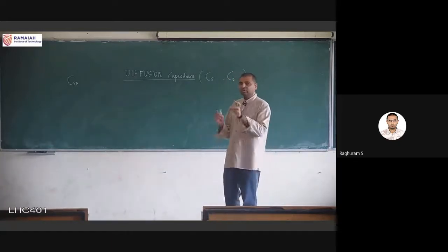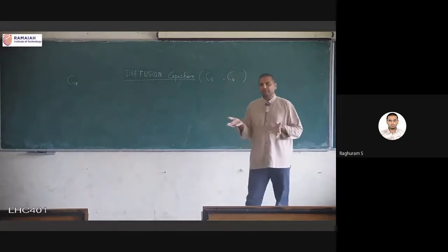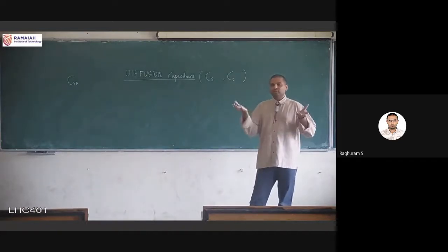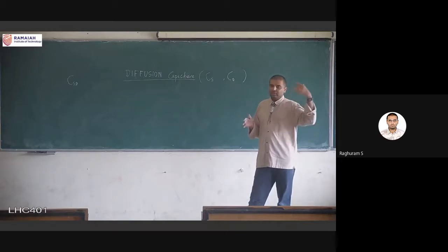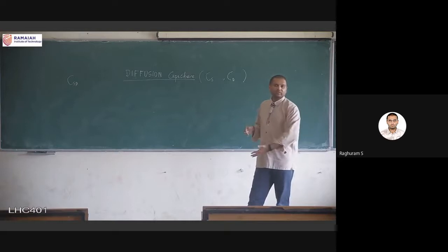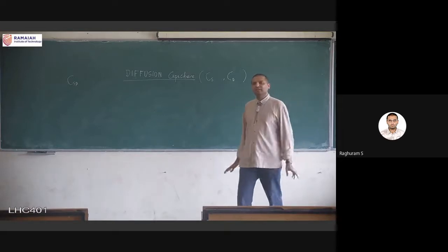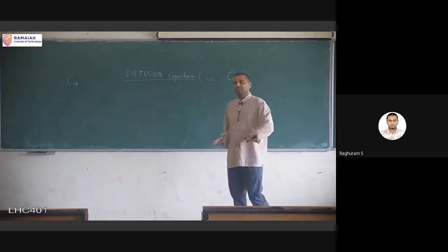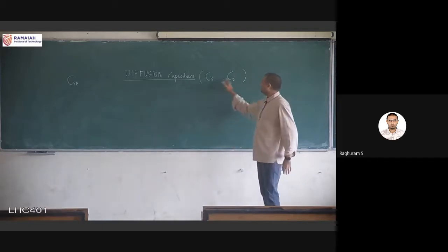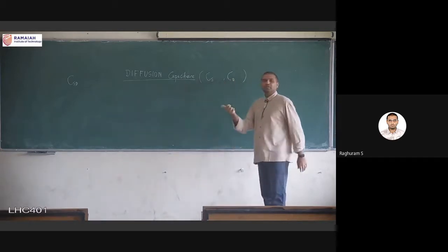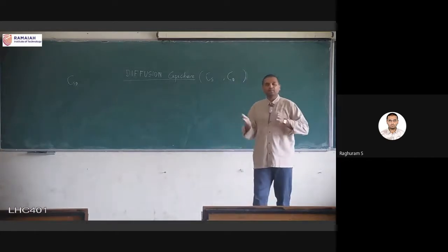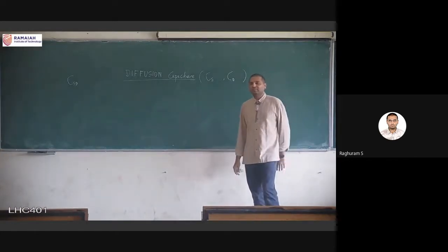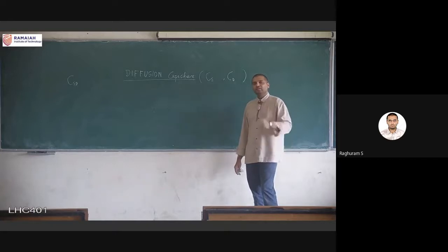These are two capacitances, both very similar in nature. Because the source and drain are very similar in nature, the capacitance associated with them is also very similar. You can call it the source capacitance or the drain capacitance. In general, it is the diffusion capacitance. But what I'm asking here is, what is the other plate of the capacitor? Any capacitance has to have two parallel plates. With one plate, you cannot have a capacitor. So what is the other plate?